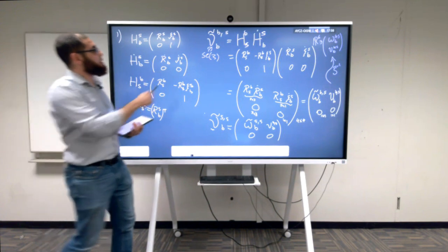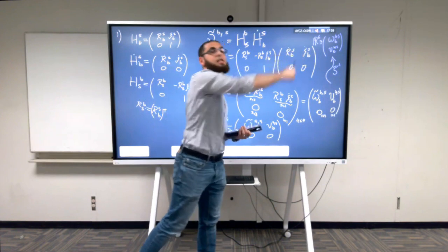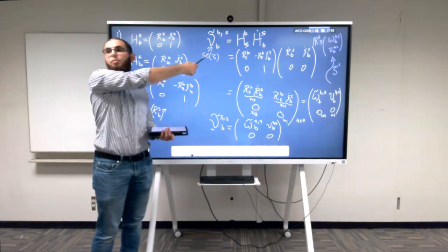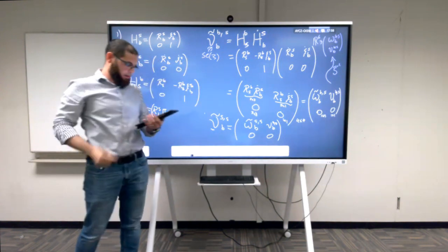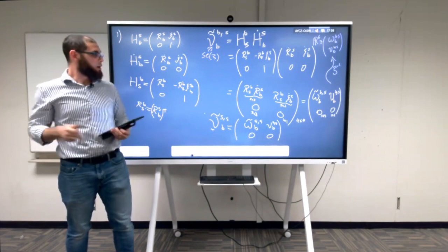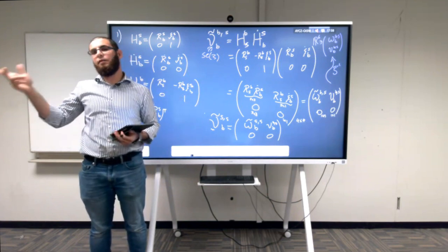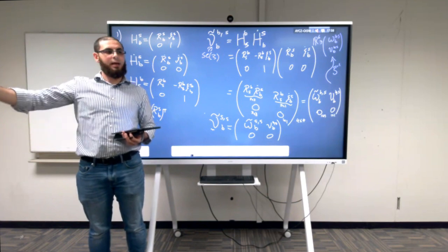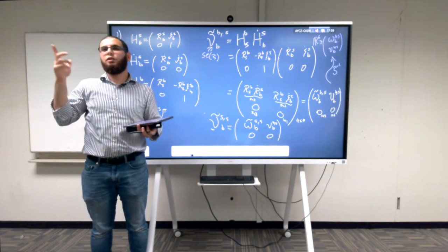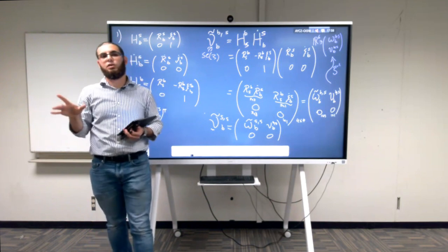Now, this is the matrix form of the twist, and this is its 6-dimensional vector form of the twist. So 6-dimensional, and this should also be 6-dimensional. It's just some 4x4 matrix written in this form. Now, there's a question that will definitely come to your mind. These two should be related to each other. If I have angular velocity represented in frame S, of B with respect to S, and I look at it in frame S or in frame B, there should, of course, be some relation, right? What do you think, looking only at angular velocities?